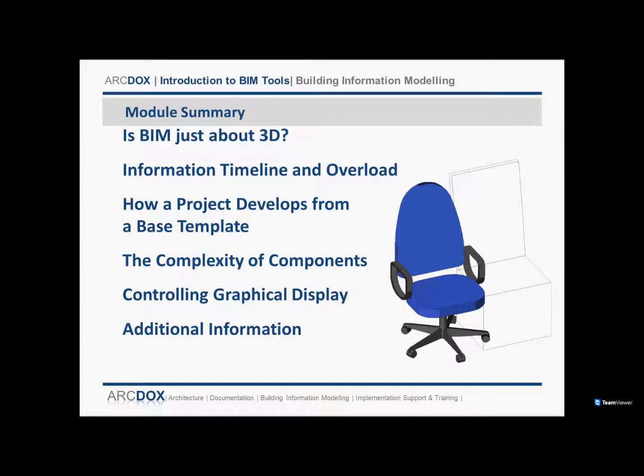about the BIM coordinator. So if you download any families or anything like that, you don't want to bring them in. It may look fantastic, but this actually relates to overloading a family. If you downloaded a complex window, and it had everything, the screws, the bolts, hangers, all sorts of hinges, that would be quite a heavy model, and in my view, too heavy. It would have to be simplified a good bit before I'd want to have that in a project I was working on.